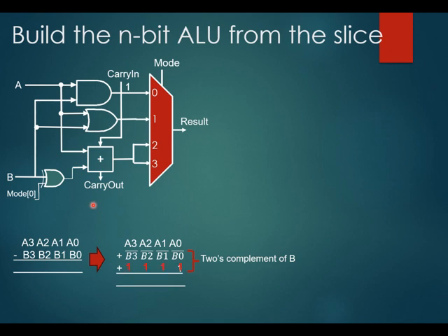This is because we cannot put the plus 1 in the carry in of the ALU slice. If we do so, and then we duplicate this ALU, say 4 copies, to perform 4-bit subtraction, then we are getting into trouble because we have a fixed 1 at the ALU slice, and this 1 will add 1 for each slice of the ALU, which is slice 0, slice 1, slice 2, and slice 3. This is not what we want for the two's complement process, because it just needs a plus 1 at the least significant ALU slice.